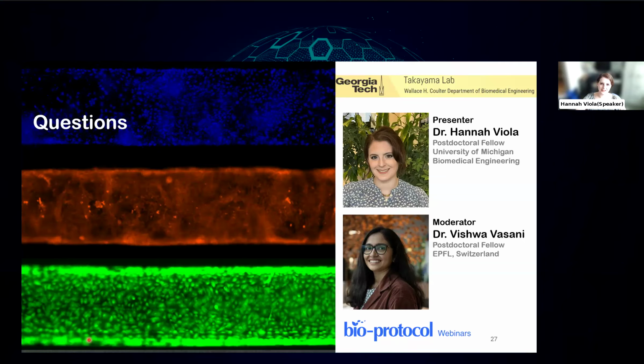And if your cut is not optimized, if you have too much chip load or you have an accidental collision, which can happen, you might lose a tool. We have a tool graveyard. It's okay. You don't want to break a tool, but it happens every once in a while. They're not insanely expensive. So it does happen, and that's part of the optimization process. And one of the reasons that you want a good optimized cutting plan is so that you're not putting as much strain on your tool and you're not as likely to break it.